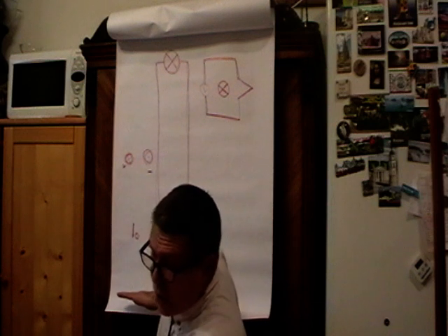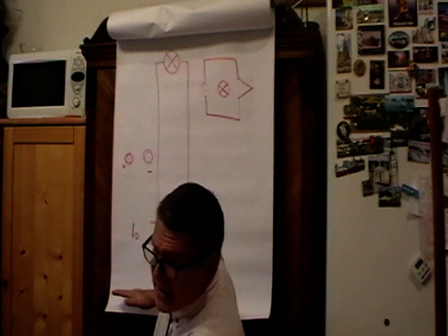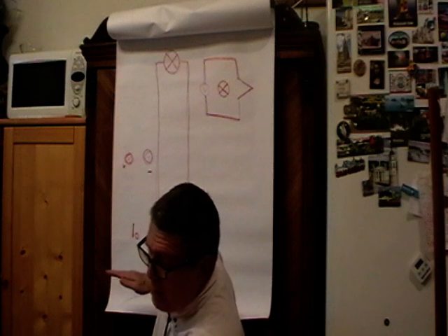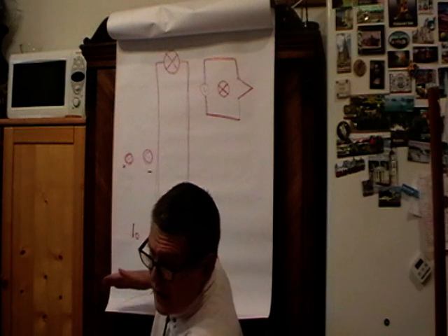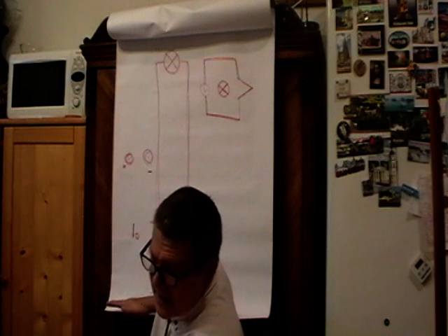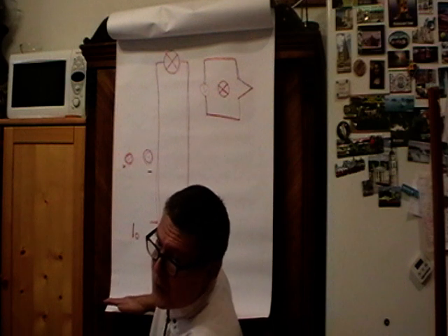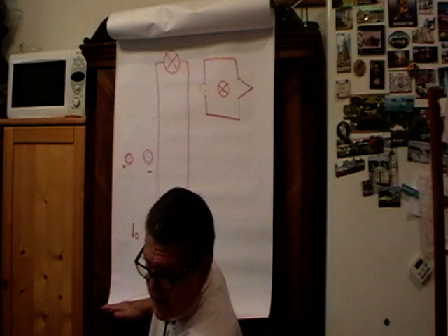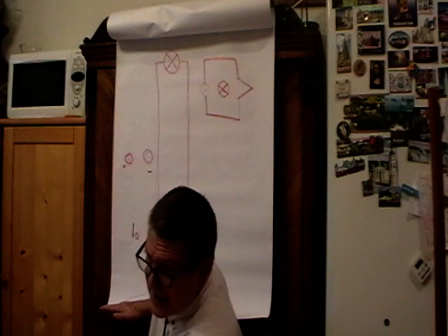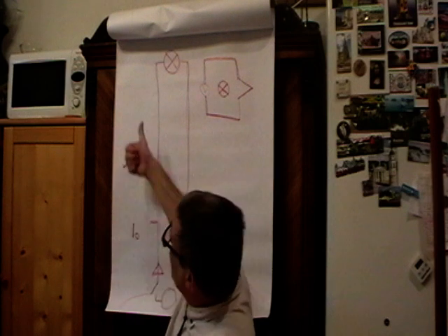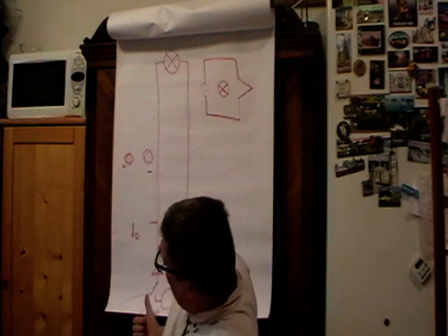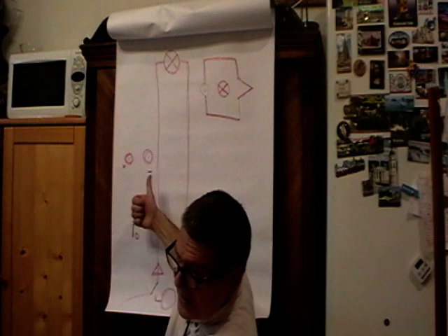It reaches the source. A source, a perfect source, is similar to a perfect short for any change. So if there is a wave that reaches it, it reflects it like a short, that is in-phase current, antiphase voltage. And we have now three waves, the original, the reflected, and the double reflected one on the line.